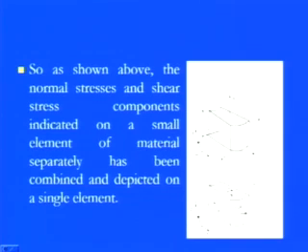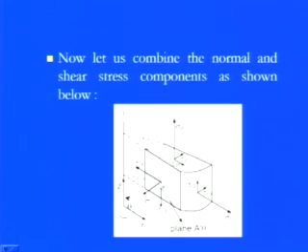So now it means that we have 9 different components, irrespective of the Cartesian coordinate or this polar coordinate. We can simply describe all 9 components combined in polar coordinates, or cylindrical coordinates, like this. This is the theta domain. In the theta domain we have sigma theta theta, or, as I told you, there is no need to go to the 2 subscripts. Only one subscript is essential to describe this normal stress component.